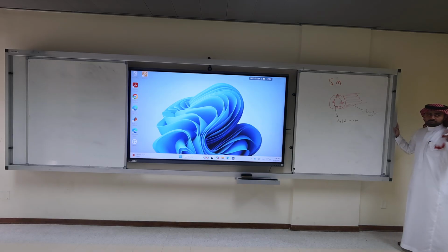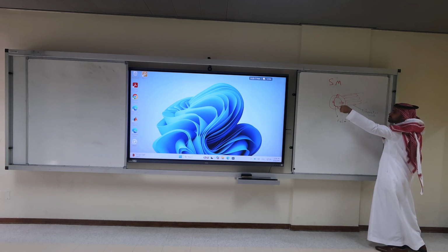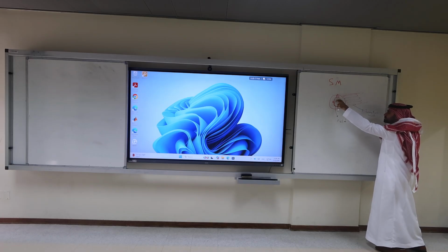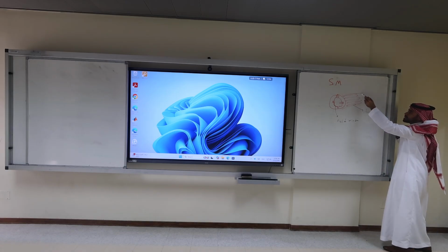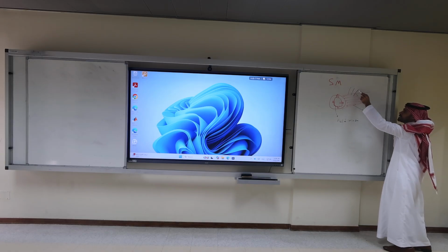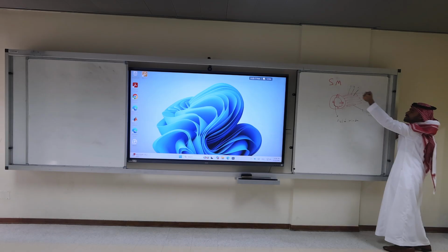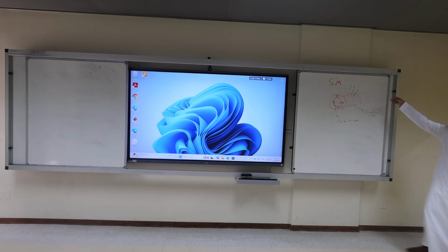For example, in the synchronous generator, when you move the prime mover using any sort of mechanical energy input, the magnetic field on the rotor would induce voltage on the stator, and you get your terminal voltage. Usually you get here A, B, C. You get your 3-phase voltage output from the stator. For a synchronous motor, you reverse the operation. You apply 3-phase, and then you spin the rotor at a synchronous speed.